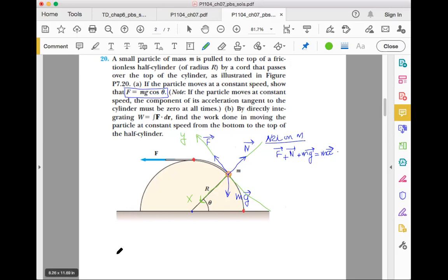But as we have seen, if you have two axes which make an angle theta between them, then if you take the perpendicular to the first and the perpendicular to the second, you would have the same angle between the two as well. And this is what I'm going to apply here. So the angle theta is between the radial line and this horizontal. mg is perpendicular to the horizontal, right? mg is perpendicular to the horizontal. That's the first line. And then we know the y-axis is perpendicular to the radial direction. So this is the angle theta between mg and the y-axis.